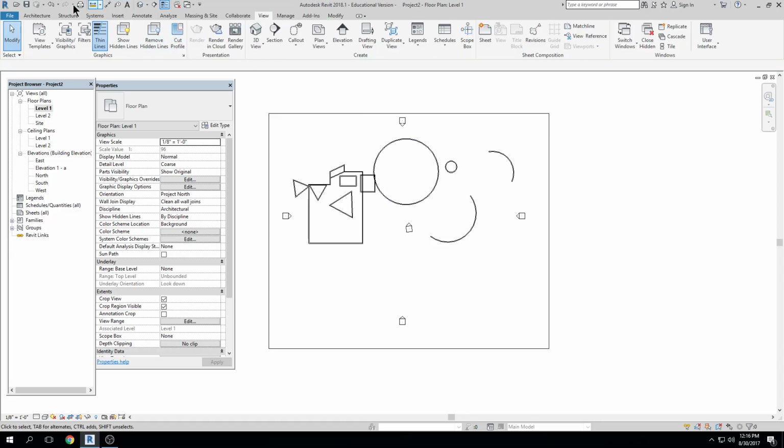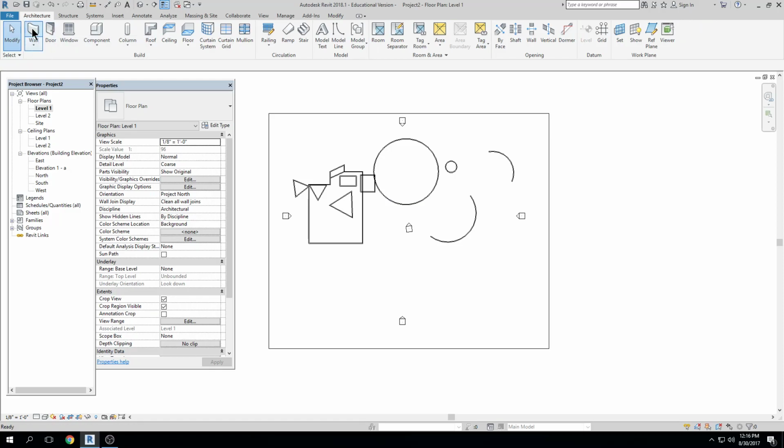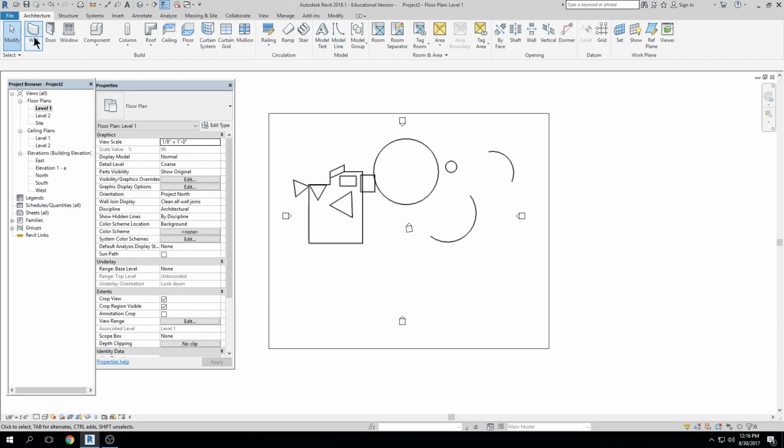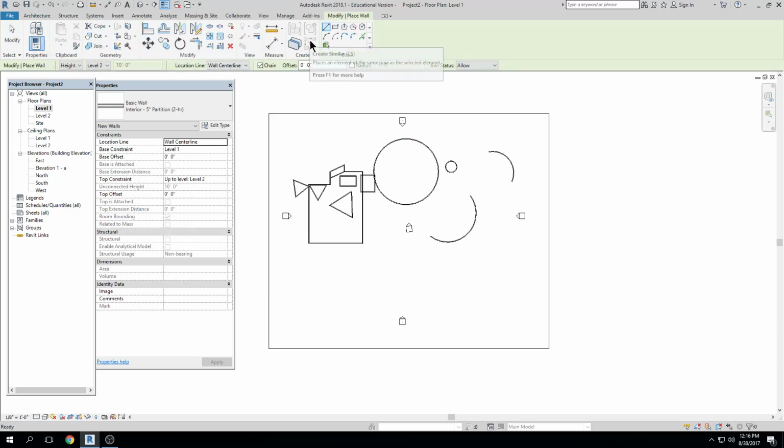All right, so we'll look at one more drawing method today. And that is going to be, oh, I did something good. Now it erased that error. Anyway, I'm going to choose the pick method to create objects. All right. So if, for example, I have an exterior wall here, and I think to myself, well, I want to have another wall 6 feet away from that wall. Okay. I can use the pick method to draw objects.